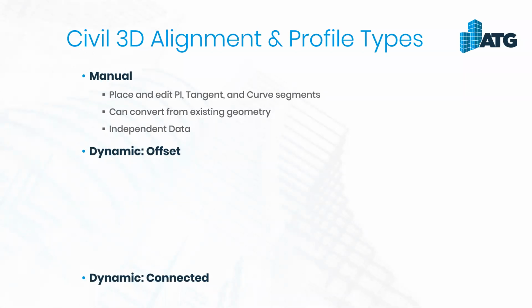And these are going to be dynamic. And so with this, you're going to follow another alignment. And the benefit is that you're going to have intelligent offset and curve interaction. So when I'm 12 feet away and I'm on an inside corner, my radius of that corner will automatically be 12 feet shorter than the center line or than the parent object. And that exterior corner is going to have that 12-foot radius added in on top of that. If my parent object changes, so too does my offset object. So it's going to track all of that geometry for us.